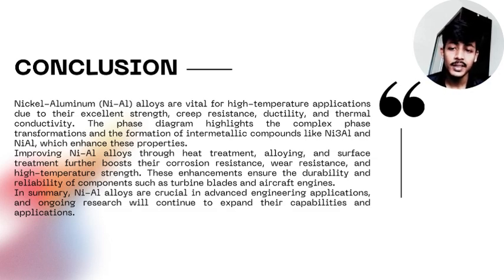The formation of intermetallic compounds such as Ni3Al and NiAl, as highlighted by the phase diagram, significantly enhances these properties. Further enhancement through heat treatment, alloying, and surface treatment improves their corrosion and wear resistance as well as their high temperature strength. This improvement ensures reliability and durability of critical components like turbine blades and aircraft engines. Ongoing research will continue to broaden their applications and capabilities in advanced engineering fields.